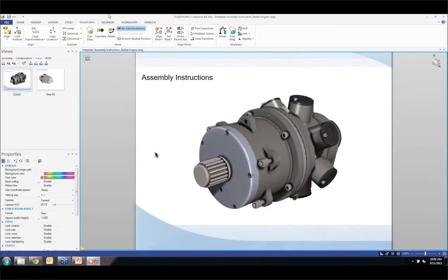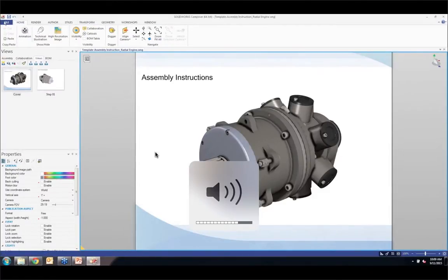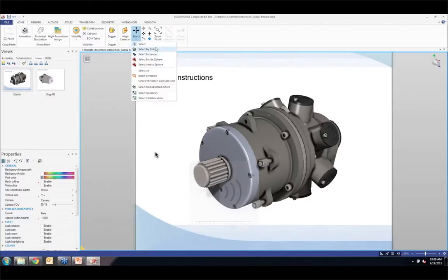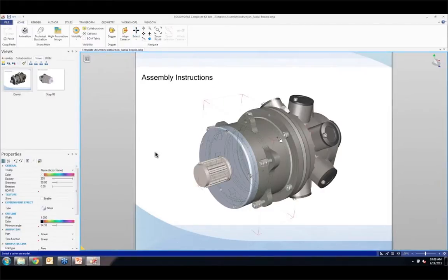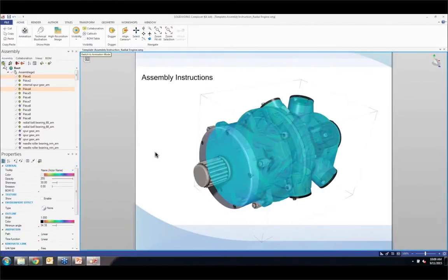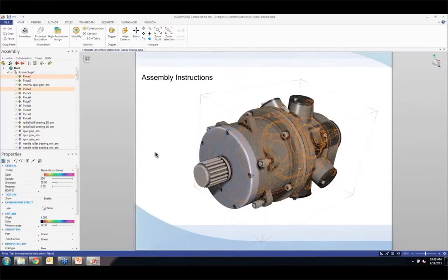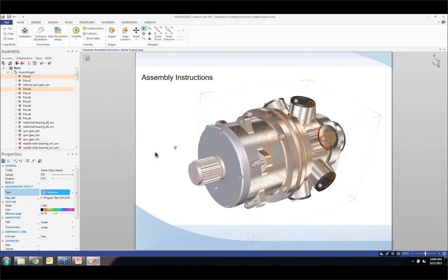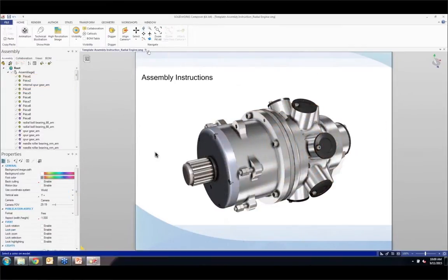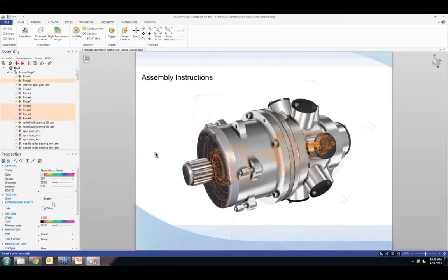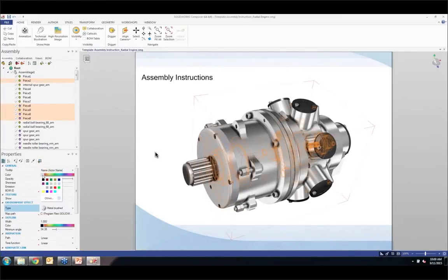The easiest way to spice it up is if you go to Home, select by color, and then we go through and just select these individual colors. Let me try that one more time here. Select by color, this guy there. So this here, I can say, okay, well that is going to be aluminum or something like that. And if I select by color this guy here, I can say, well, this guy is going to be metal brushed. And then I can control the color of that too, to get a little more defined and look like metal.